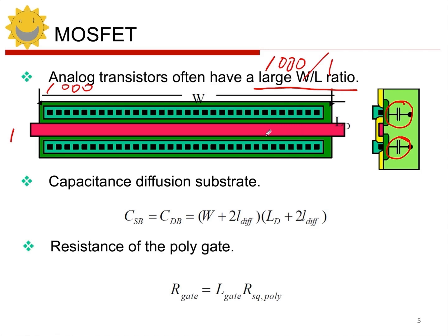That's the first point. The second point is that the gate will be particularly long, right? The gate will be especially long. So we previously talked about how to connect the gate, right? We have to connect it to a contact and then to the metal. So I can draw a contact at this position, and then I'll use this metal, M1, for example, to connect the gate out. So in this way, my gate is electrically connected, right? But there's a problem. The parasitic resistance of this gate is relatively large, right? We've also talked about how the gate's sheet resistance is relatively high, reaching up to 200 ohms per square.